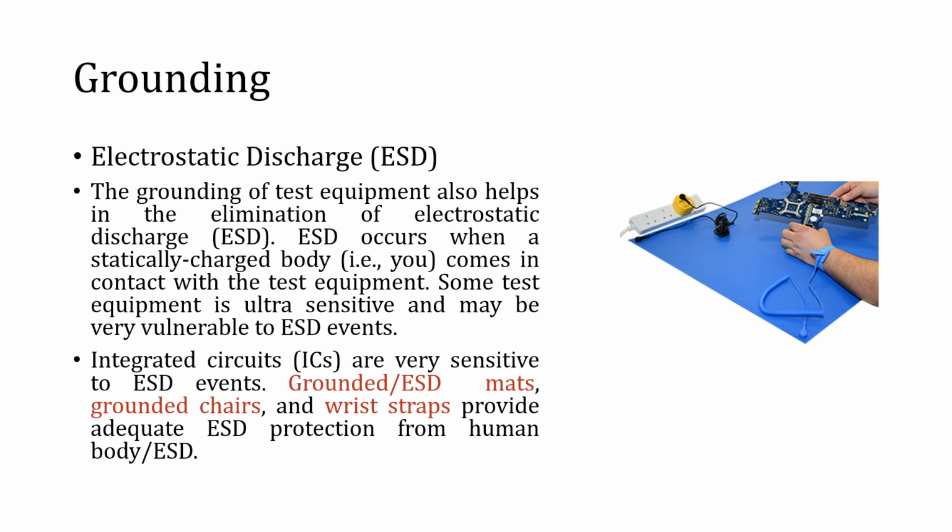If you have come across some sensitive devices or circuits, you must have seen that a few of the devices are wrapped in yellow envelopes, or there is a very large yellow sticker, and on that yellow sticker there is a symbol like this. That yellow sticker pasted on the envelope means the circuit board inside is very sensitive to electrostatic discharge. So be careful whenever you are handling those ICs, batteries, memories, or circuits.